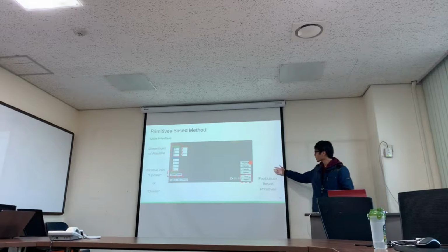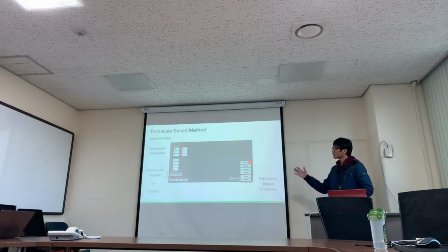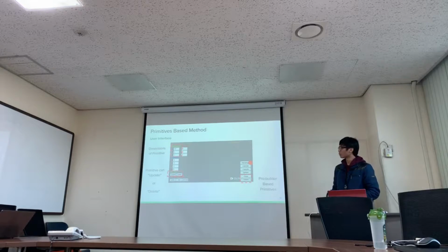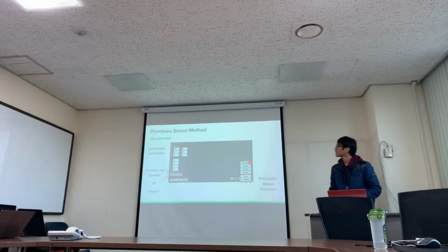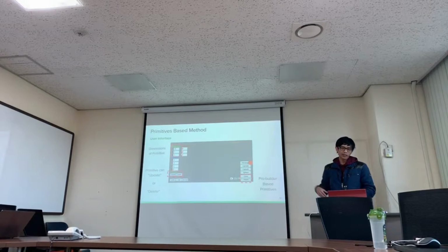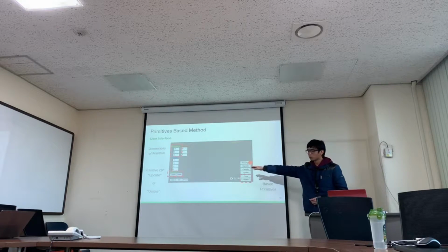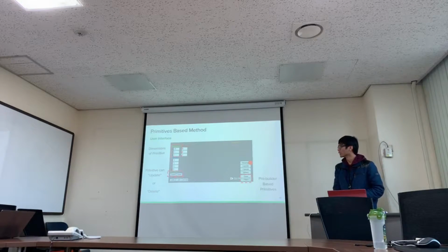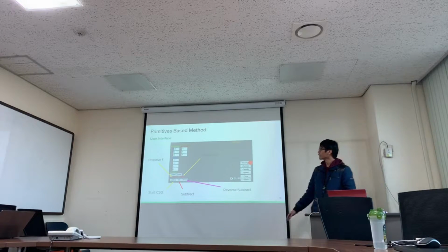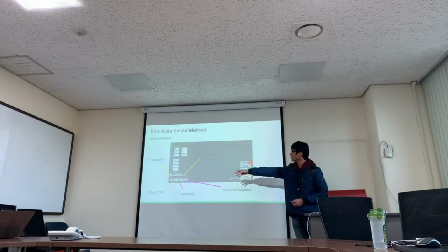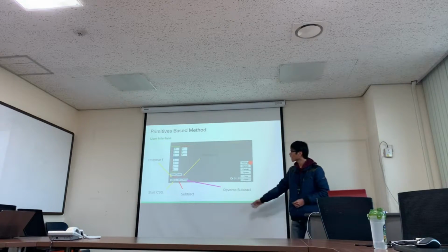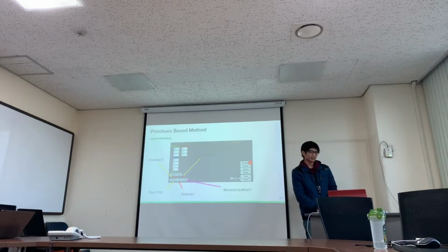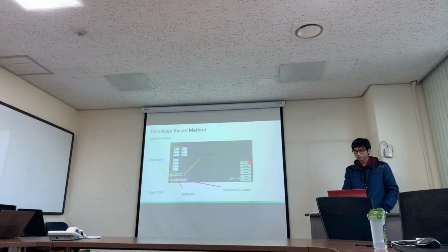And this one is a ProBuilder based primitive, which is not another application, it's an asset add-on for Unity that we utilized. And that one is where we define the dimensions, and we will just press these buttons to update or delete. Then the information regarding your solid model will be displayed in that position where primitive 1 and primitive 2 is. And then you can further edit them using those 3 buttons using a CSG method.